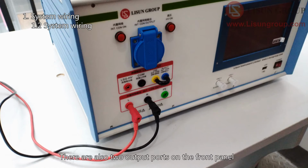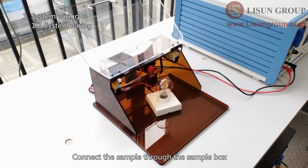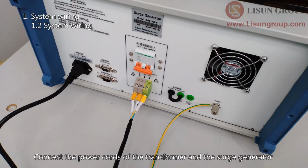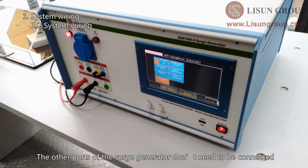There are also 2 output ports on the front panel of the surge generator used to connect to the sample. Any one of them can be used. Connect the sample through the sample box. If there is no sample box, you can directly connect the sample. Connect the power cords of the transformer and the surge generator to the power source. The other ports of the surge generator don't need to be connected.